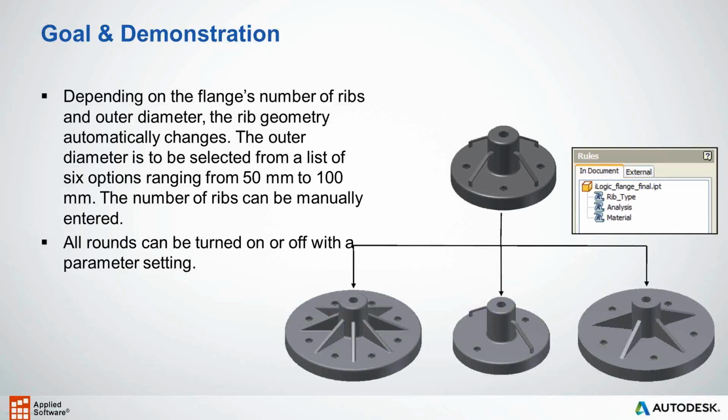If these rounded edges or fillets are really small, dealing with simulation, when we have small entities such as that, that can lead to long simulation time, waiting for the model to perform all of its calculations.